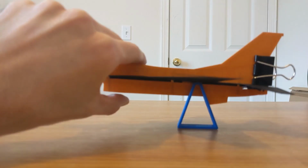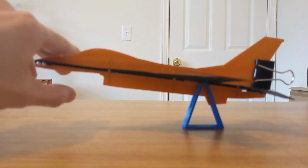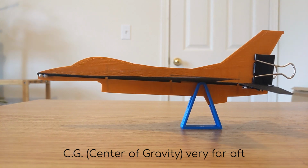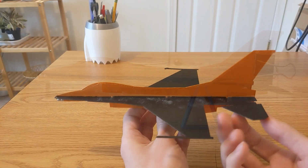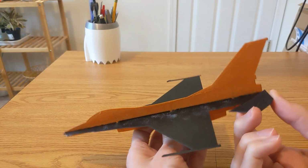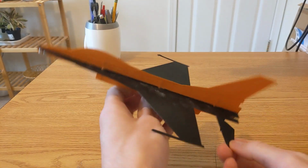Arguably more important than the weight is the location of the center of gravity along the length of the fuselage, since this affects the airplane's stability. If the CG is too far back, the airplane will be statically unstable, making pitch control extremely difficult by hand, because the airplane will constantly want to pitch up or pitch down.